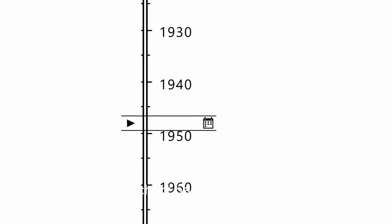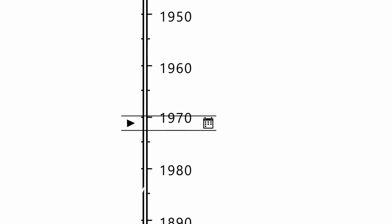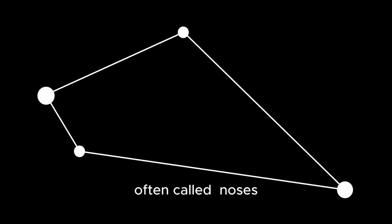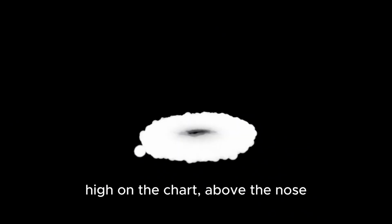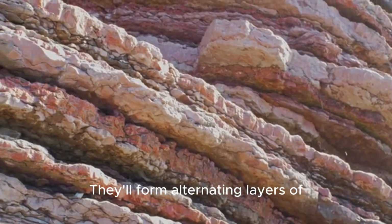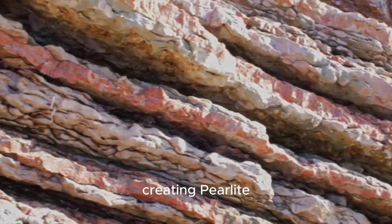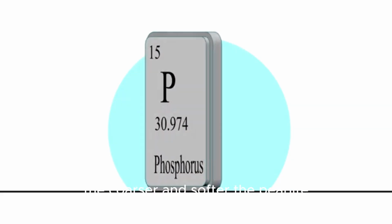Let's break down the TTT curve. The chart has temperature on the vertical axis and time on the horizontal axis, usually on a logarithmic scale. You'll see these C-shaped curves, often called noses. If you cool your hot austenite down and hold it at a temperature high on the chart, above the nose, you give the carbon atoms plenty of time to move around. They'll form alternating layers of ferrite and cementite, creating pearlite. The higher the temperature, the coarser and softer the pearlite.